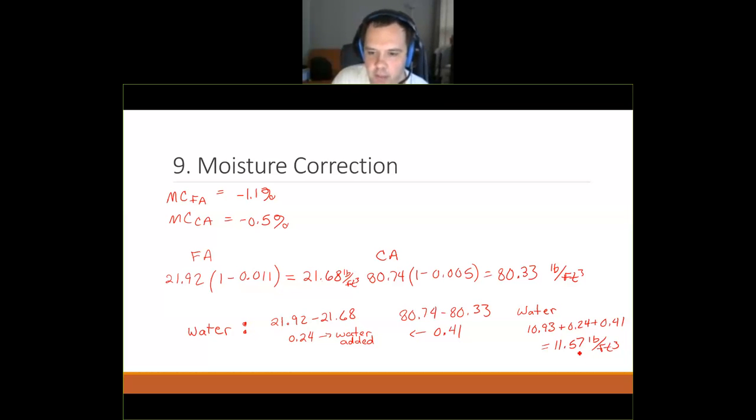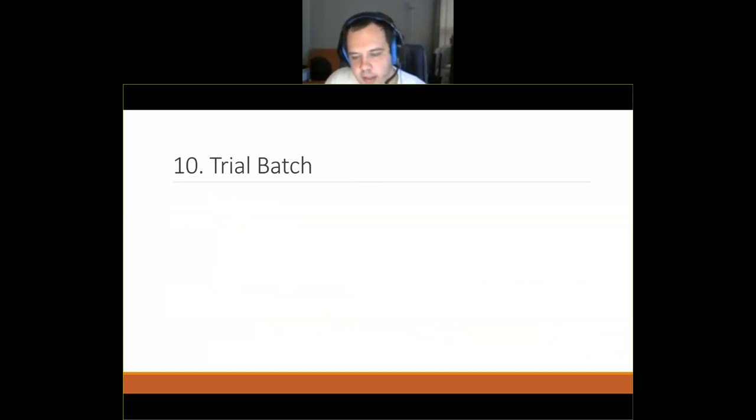These are the values that I'm going to go ahead and head into the lab, start mixing, because the next step is your trial batch, where you are going to batch it out according to your design, and then you can make adjustments based from that particular batch.